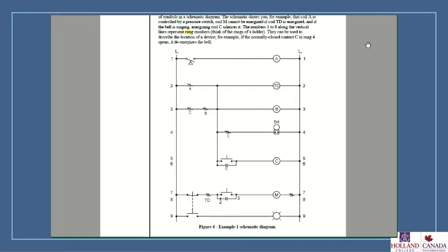Contacts and switches are shown as if there is no power on the circuit and the mechanical system is empty, no pressure on the lines, no liquid in the tank. The armature, the moving portion of the push button of a normally open push button, is drawn above the contact points. Normally closed is drawn below.